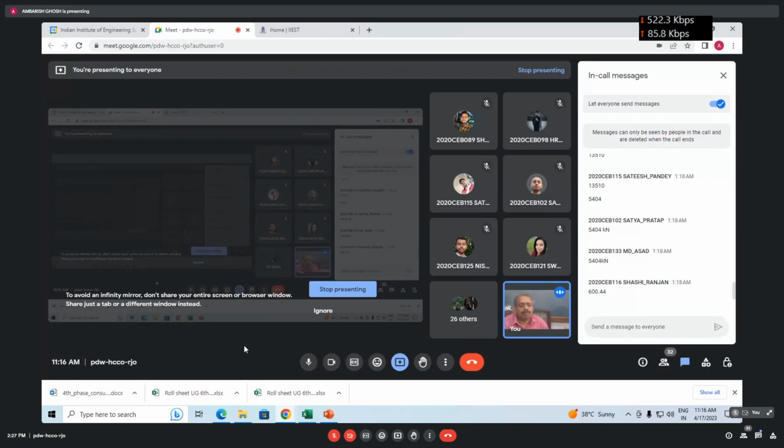So what we have covered today: first we started with the lateral load carrying capacity of pile. As per IS 2911, you have already calculated the lateral load, how to get the moment, how to multiply it with the modification factor, everything you have done on your own today. Then we went to the pile group.